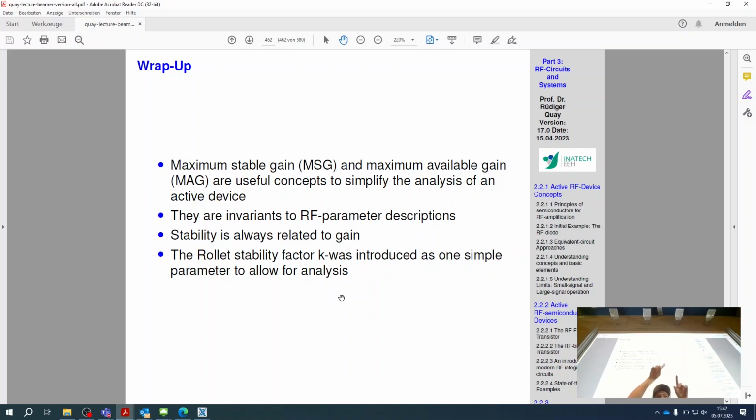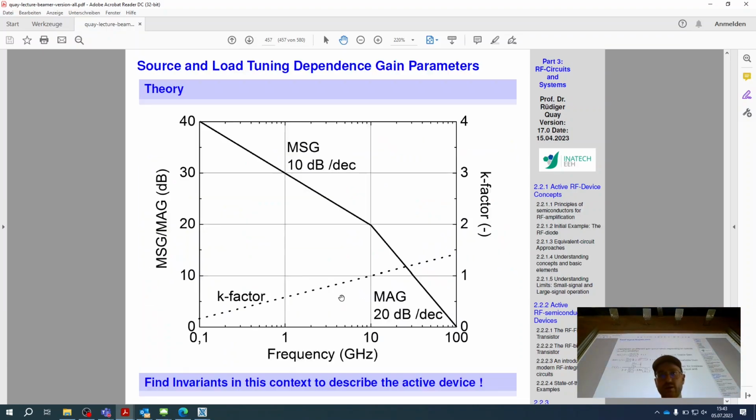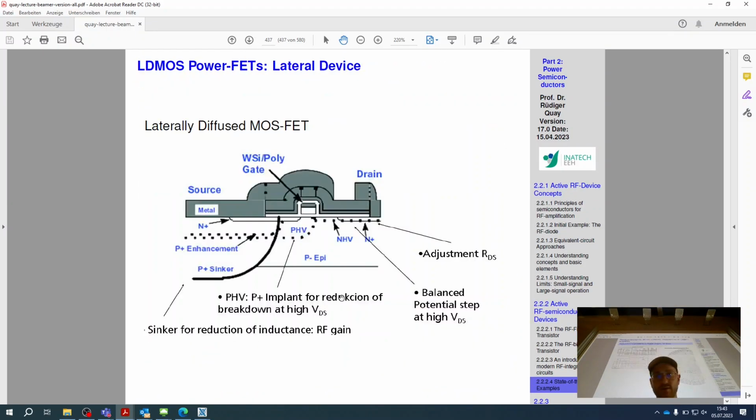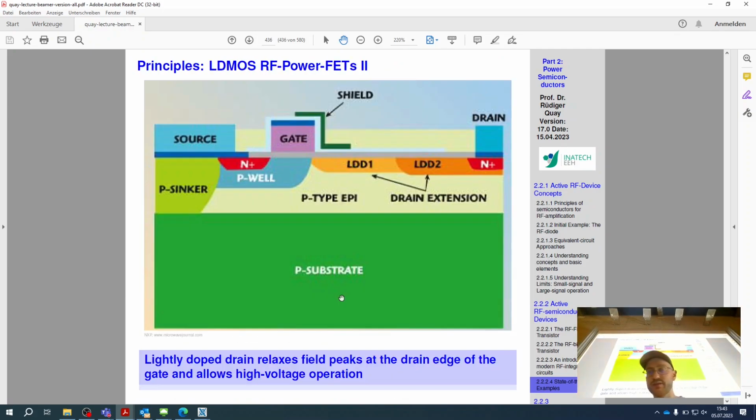And at some point, once it amplifies after a certain part, when we have this laterally diffused component, as we saw beforehand, here, for example, is the diffuse component. At some point, this will start to have a concentration of a high electric field, and that concentration will burn through the semiconductor and burn your device, because it will be too dense a concentration of the electric field for the device to handle. So the physical structure will simply tear. The physical connection between the atoms will rip. You will have issues with contact ionization and so forth. Then your device will just burn out.